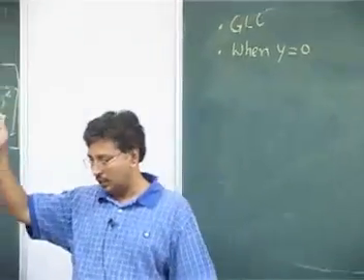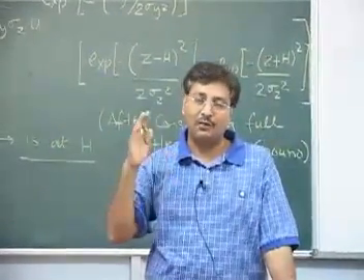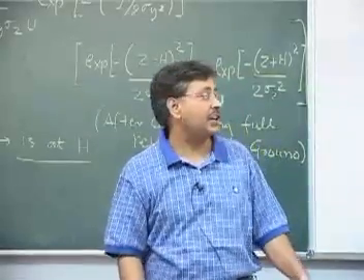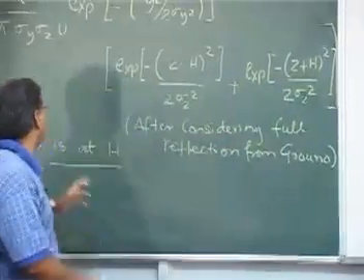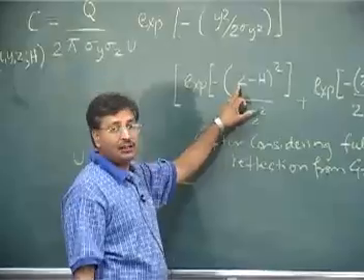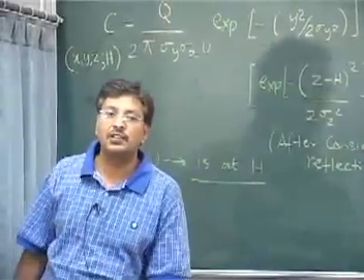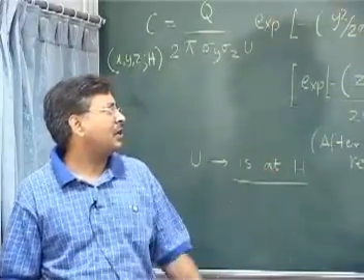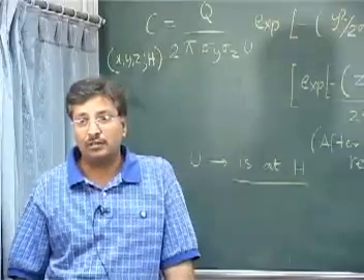Suppose the plume was passing over IIT Kanpur from the Panki power station. Then I want to say, well, what is the concentration for the people sitting at IIT Kanpur, taking y equals 0. So the simple thing you do here is put y equals 0 and z equals 0, and you come up with another expression. And that expression is most commonly used, because that's where we want to find the ground level concentration, that is when z equals 0 and y equals 0.